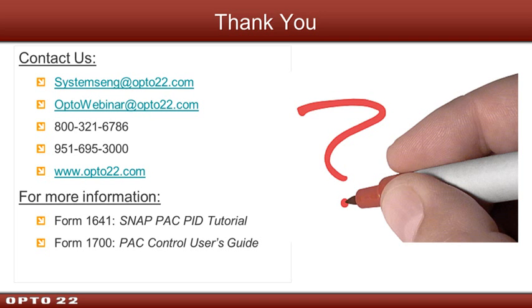Yeah, the scan rate is very important, Alexi, and that's why I took the time to explain it. Because you want the loop to be responsive, but you don't want it to be reacting to noise. And again, that's something we're going to look at in the advanced topic of how to set up your PID loop to take its input from a filtered analog input.